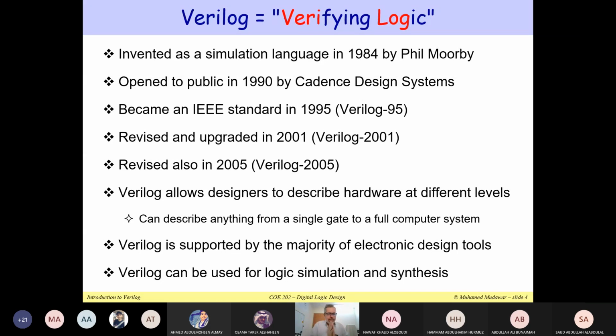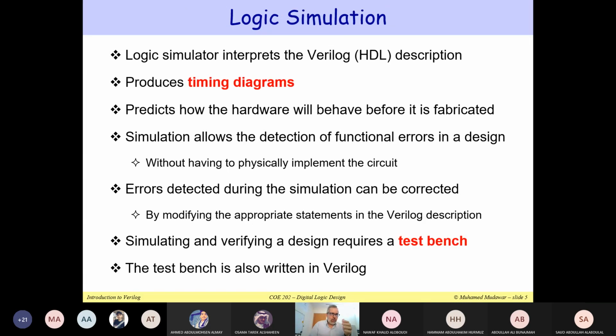That's really very interesting. In fact, we have a variant of Verilog called System Verilog, if you would like to describe large systems. Now, Verilog is supported by the majority of electronic design tools. There are very expensive tools that you can use to design chips, and these support Verilog. We can use Verilog for logic simulation and for synthesis. So let me briefly talk about the difference between simulation and synthesis.